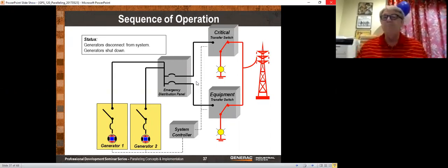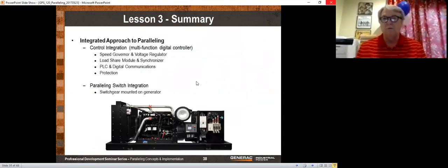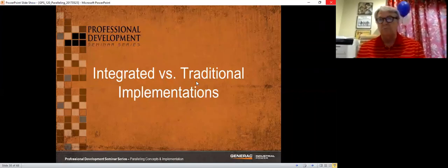So you will hear, and then it'll stop, and then you hear click as the first contactor clicks, and then all of the rest of them synchronize. It takes a second or two, and then you hear, and all of the other generators parallel. Our system at the University of Utah, I'll show a picture of that, has 10 generators in parallel. Typically from power outage to all generators online and parallel is approximately 7 seconds. And that's kind of unheard of with traditional paralleled systems.